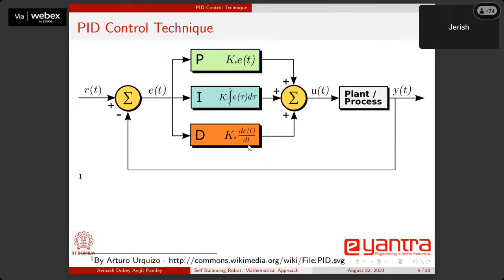So it's basically like predicting the immediate future of the system behavior. The future behavior can be determined by the derivative controller. Based on that, whether the error is going to increase or decrease can be predicted by the derivative controller, and it can be controlled using the derivative part. So a PD controller basically reduces the overshoot and the oscillation, and it will try to maintain the set point.